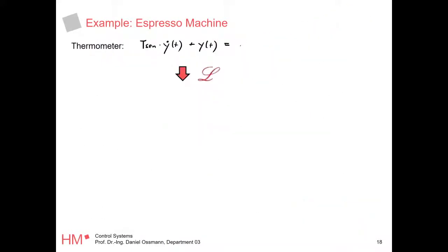And obviously it takes in the actual, the real water temperature. So there is a small time delay between the real water temperature and what we measured. Kind of makes sense. What is notable here is that you should have a 1 here, right? Because it does not make sense that if the water temperature is 100 degrees, you measure just 50 degrees. Then you would have a 0.5 here. A steady state gain of 0.5 does not really make sense for a sensor.